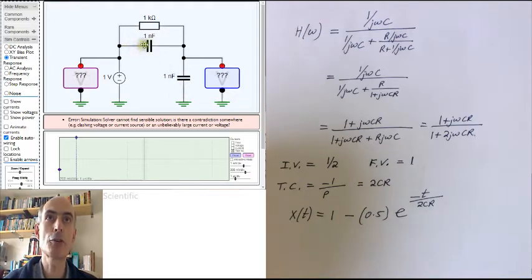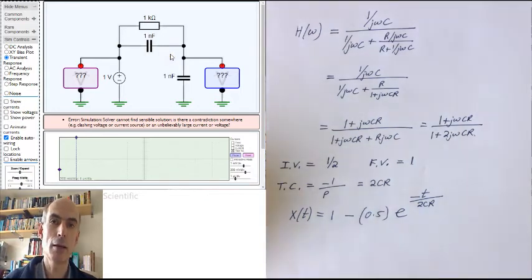And if both capacitors are charging up by the same amount, then the voltage here, where they join, will be half of the voltage at the point here where the step arrives. So the initial value that you would observe in the lab would be a half.